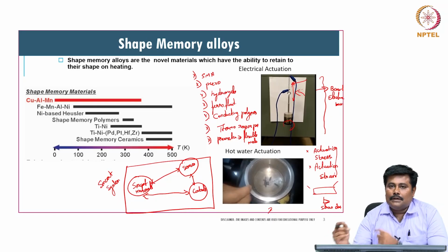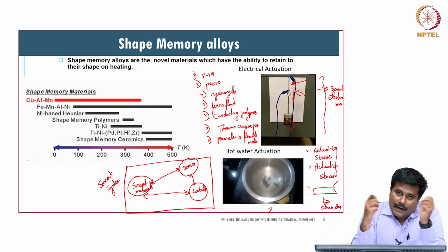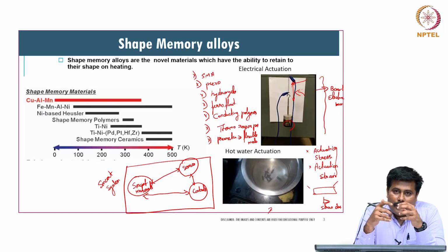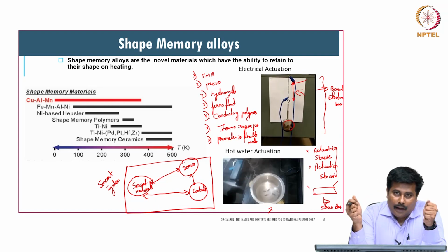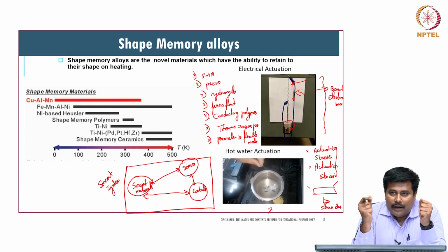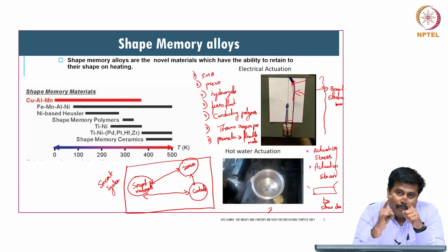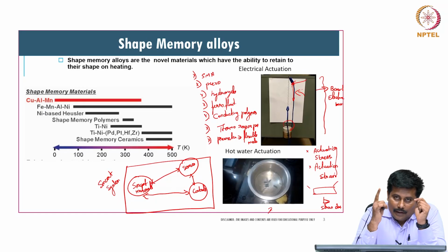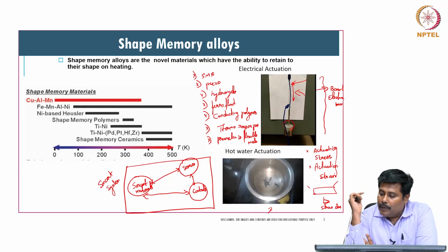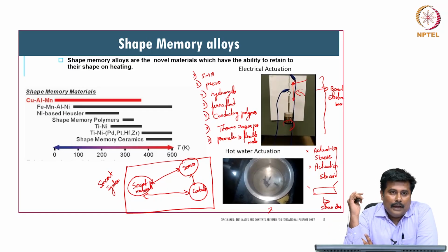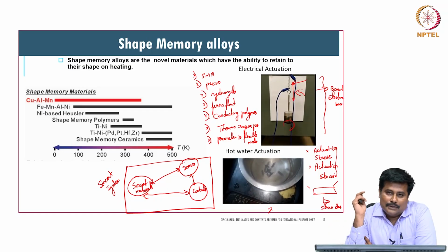Let us consider we are enlarging the shape memory alloy, and it is completely in an elongated phase, and then when I supply heat, it will try to come back to its shape. The position to which it needs to come back can be appropriately restricted by applying an electrical biasing to this system.